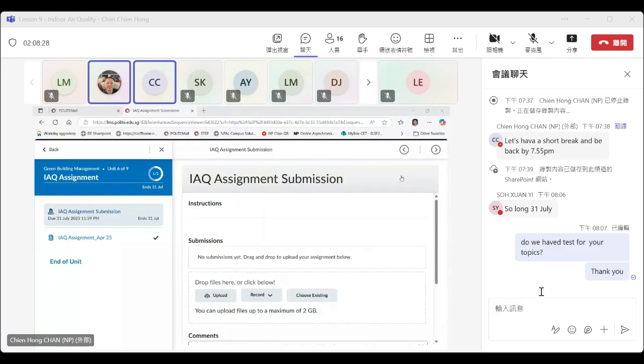Actually, there is the air well and there's an exhaust at the center. They have exhaust at the corner. 4 corners and at the center. Apparently the center one was spoiled. Poor maintenance and it wasn't working. So it left the 4 corner exhausts, and the 4 corners can't do much because you need to be directly below the exhaust, then it is able to suck out. If you are in the center of the building, too far, cannot. That's the problem. I always got fire alarm activated.